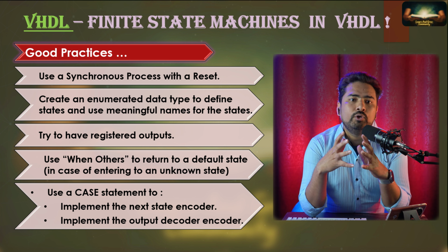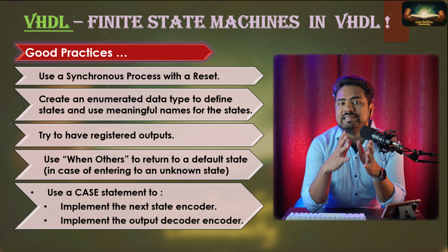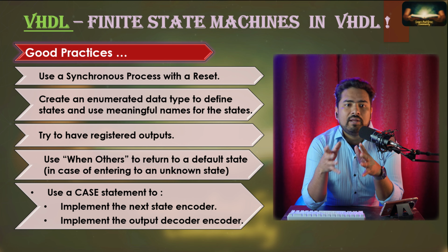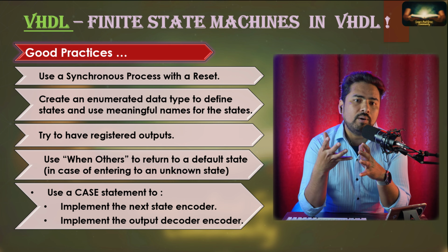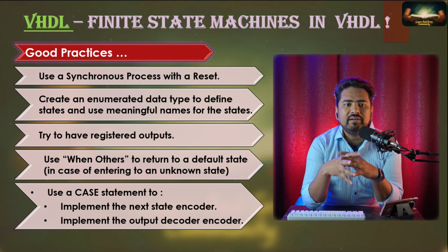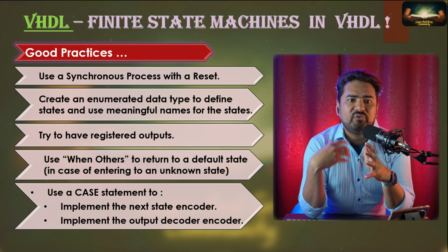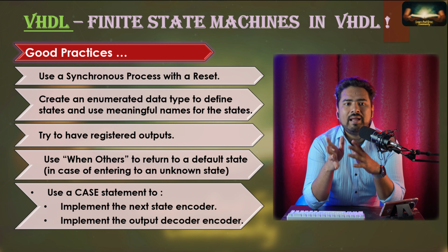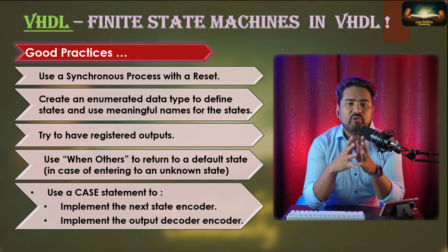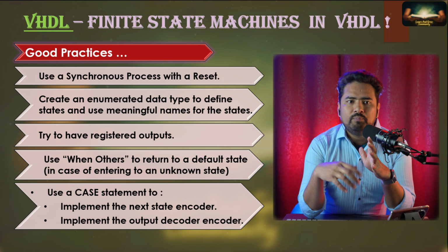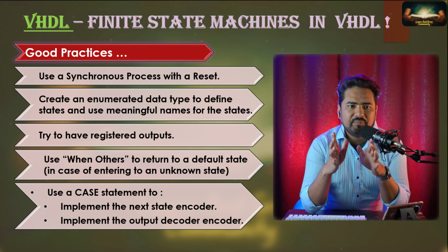As I said, you can split your code between two separate register process blocks for defining the output of each state and defining the next state. Otherwise, you can also combine both things into one register process block, like we did in our example. If you feel that is complex, then simply split it into two register process blocks and it will not impact any hardware performance, and it will be easy to read as well. So both ways are completely fine.